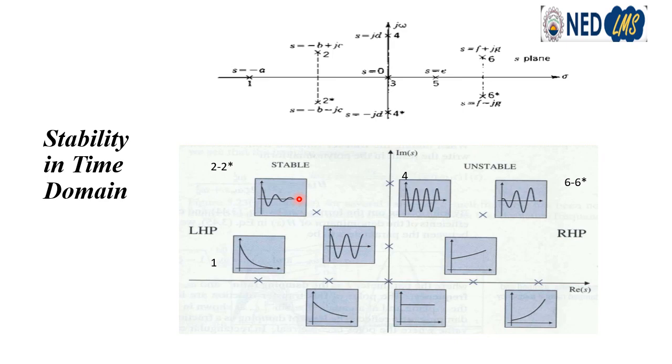So we notice here that when we have an imaginary part in the root, we have some oscillatory part in the response. And when we have only a real root, that is without an imaginary part, then we have only an exponential part in the time response. So actually the real part of the root corresponds to the exponential response, and the imaginary part of the root corresponds to the oscillatory response. But in all these cases, if sigma is negative, that is we are lying in the left hand side of the S-plane, our system will remain stable.